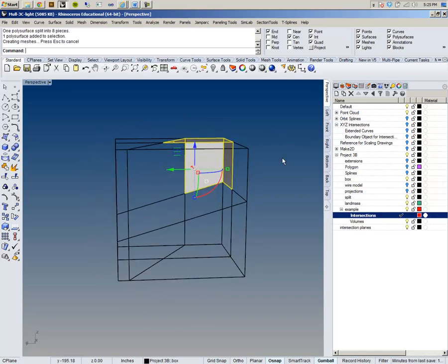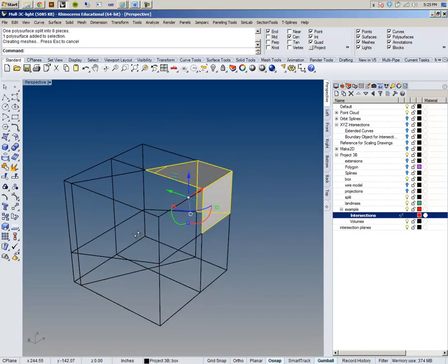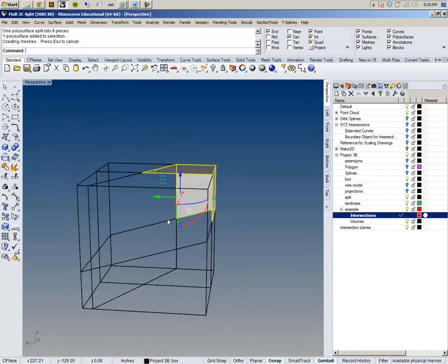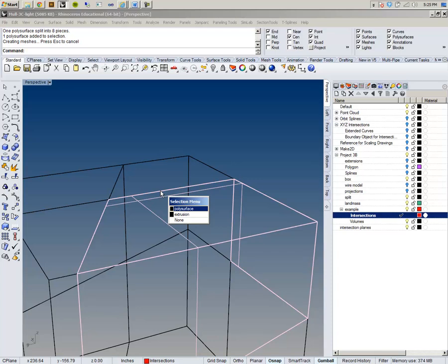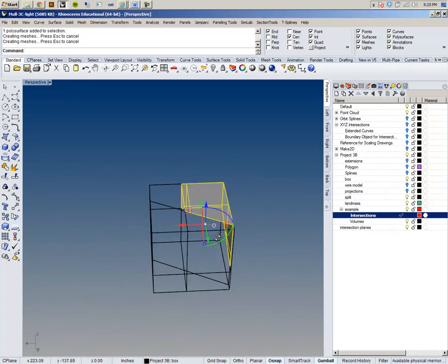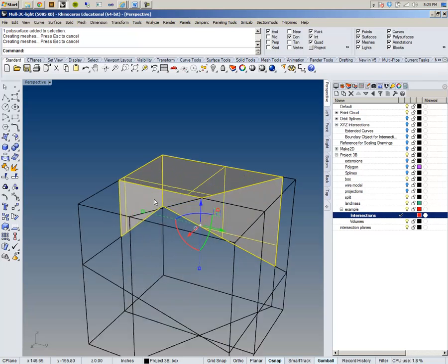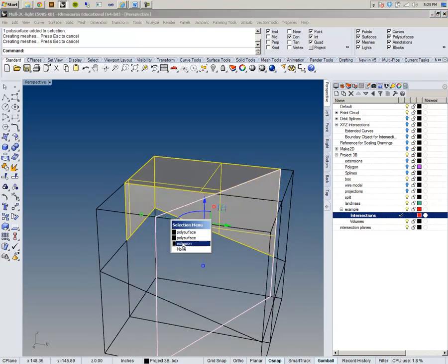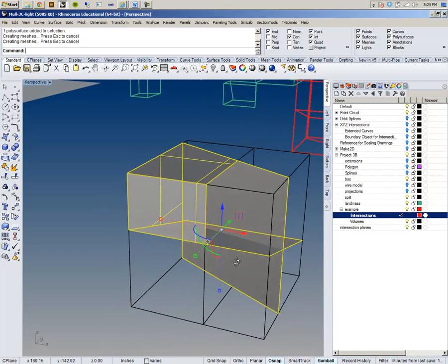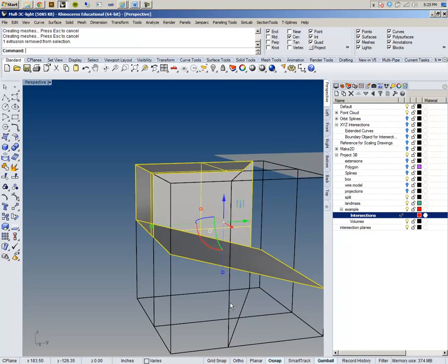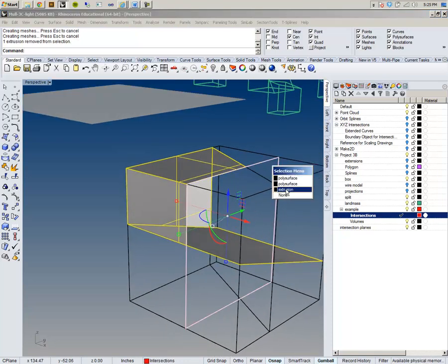You'll notice when you get those 8 pieces that they're going to be kind of open because you just sliced through. But you still have those planes there, and you can use the Create Solid tool to close these up afterwards. So now I'm left with this little piece here. They're all going to look something like that, right? I can use the resulting extrusions that I still have to close that object up. In this case, it wouldn't be the one down here, it'd be the one that comes over here. Right?